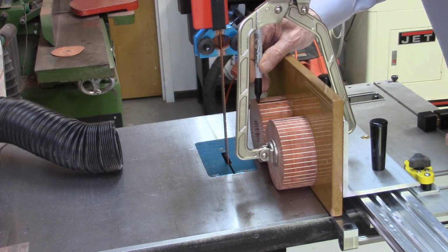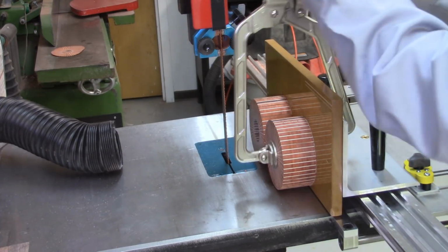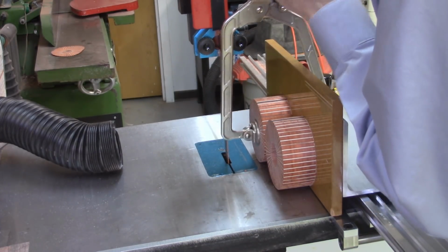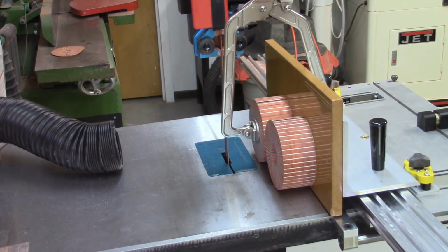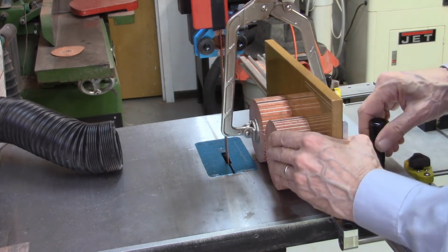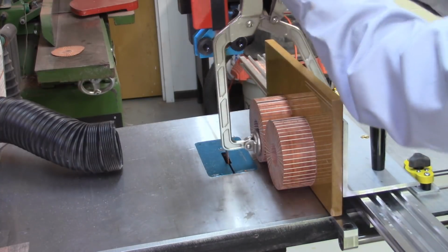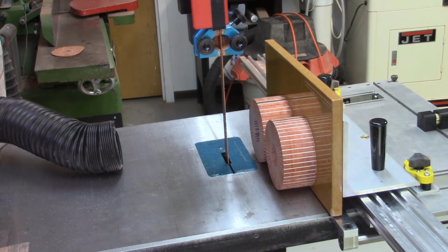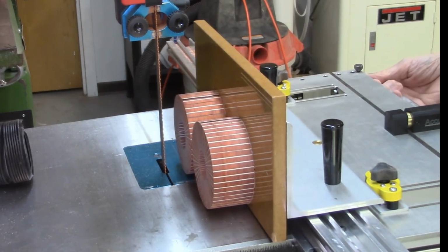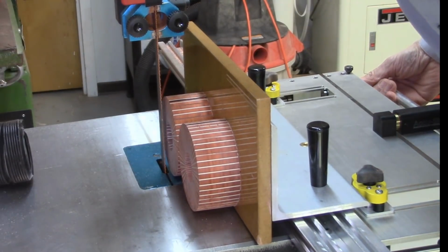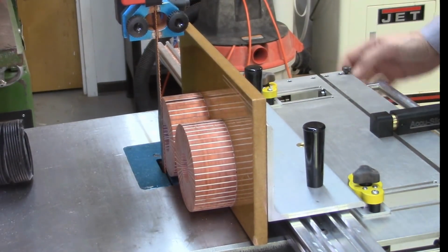I lightly clamp each of the disc assemblies to the carriage for a few seconds to thoroughly set the double-sided tape in order to properly hold the disc to the sacrificial fence of the Accu-Slice carriage. I move the Accu-Slice carriage to line the mounted discs so that they just touch the bandsaw blade, and then I lock the Accu-Slice table in place using the 2 coarse adjusting screws.